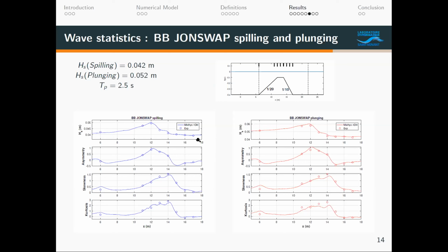And so the results are for about 15 minutes of wave propagation. We see that the significant wave height at 12 to 14 is good in both cases here. So the onset is working fine. And we see the offset criterion, where the wave breaking ends, here. We see the values of significant wave height at these gauges at 16, 17, far after the offset of wave breaking, and even these are agreeing well. So the offset criterion is working well. And the dissipation model is calibrated for spilling breakers, but we see fairly accurate results for plunging breakers as well, for this one and the earlier one we saw.